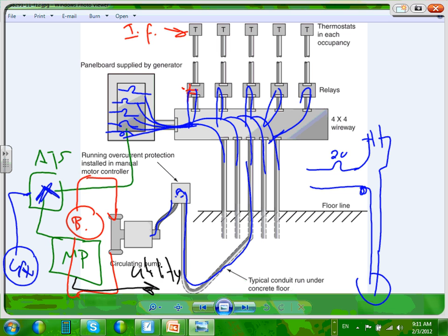The utility is coming to the main panel in this example. And the main panel is taking a feeder to feed the auto transfer switch, to actually feed this panel through the auto transfer switch. And then when that connection is lost, we do automatic transfer. Yep, something electronically. They have batteries on them.